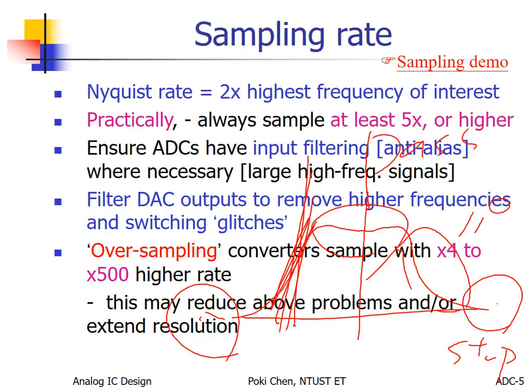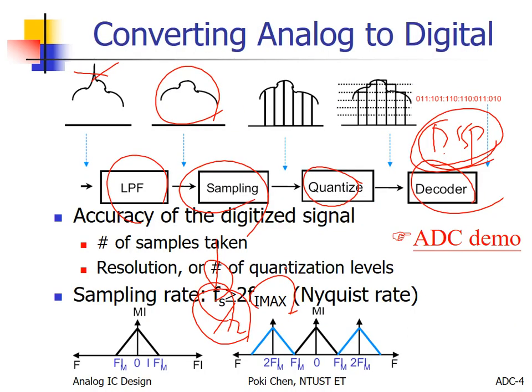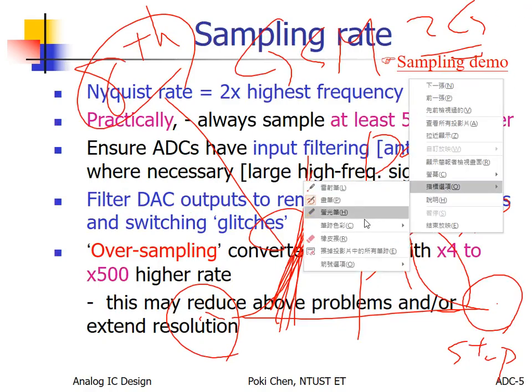All right. From the very beginning, according to GSM, that is maybe 2G, tens of years ago, we required 8th order for such filtering. It's really hard to implement in the analog domain, so usually we implement it in the digital domain. Anyway, this is also one of the answers why we like to do such coding and decoding.